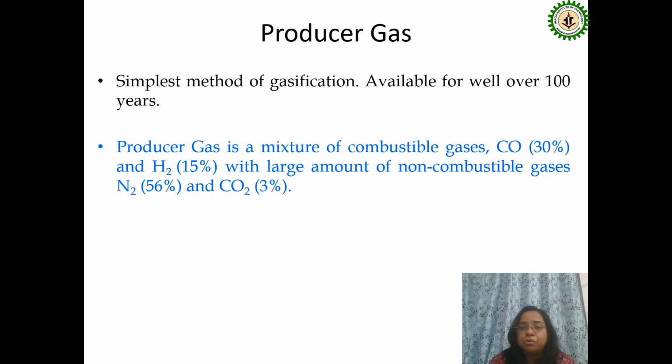A very high amount of nitrogen is present, and as we already know, nitrogen does not contribute to the calorific value. So a huge fraction of producer gas is nitrogen, which does not contribute to the higher heating value. As a result, the calorific value of producer gas is comparatively lower than the other gases.